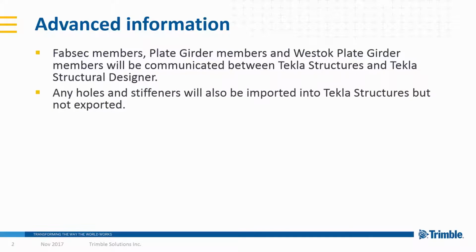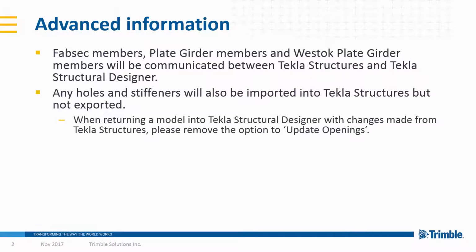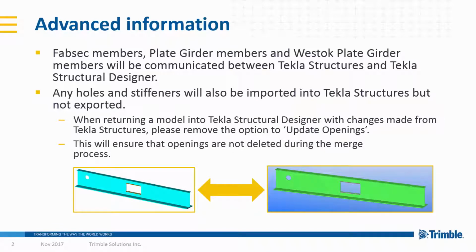Any holes and stiffeners will also be imported into Tekla Structures, but not exported from the Tekla Structures software. To ensure that openings are not deleted as part of the merge process within Tekla Structural Designer, remove the option to update openings shown in the Structural BIM import wizard. This will keep any openings within Tekla Structural Designer unaffected.